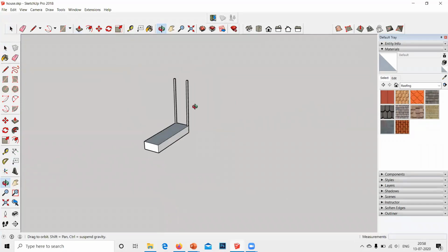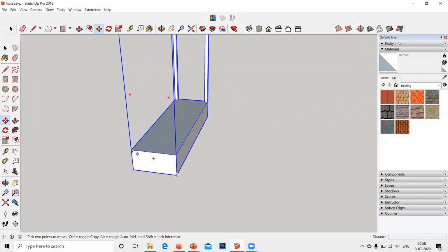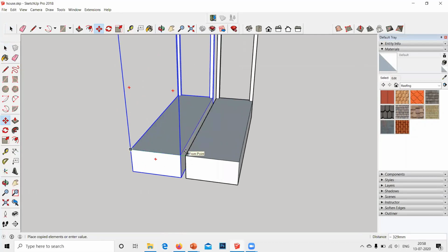We have created a stair. Use the tape measure tool. Now simply click on the left arrow key, select the move tool and enter 1000. Click on this part, press control. Yeah, I have copied it. I have made a measurement. Okay, I'll just repeat what I did here.